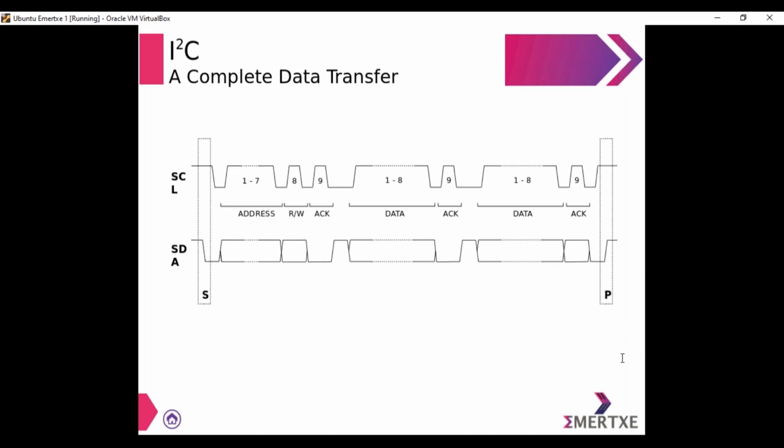Okay. If acknowledgement is to be transmitted, it's a write bit, so will it happen at the low level of the clock? And don't master and slave give acknowledgement by pulling the data line differently? If yes, how? So yes, acknowledgement is obviously a write, but it is a special condition. You don't consider acknowledgement as a write itself most of the time. So it's considered a special condition, and all the special conditions are done at the high level of